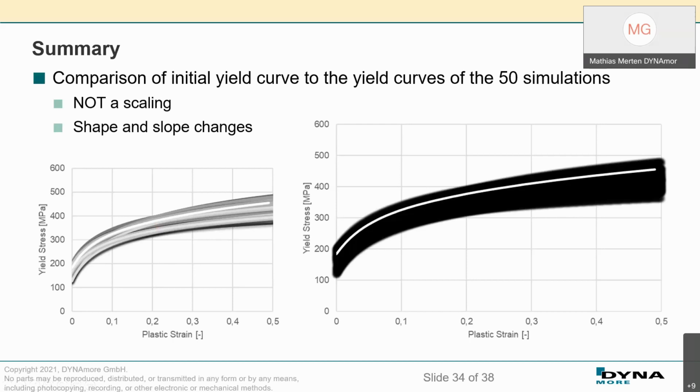This is also what you may expect from the material science point of view: they are not just a scaling, but are connected to the yield locus and to the anisotropic values. This was not taken into account by us, as we do not have reliable data available for that, or we were not able to find data in a short time.